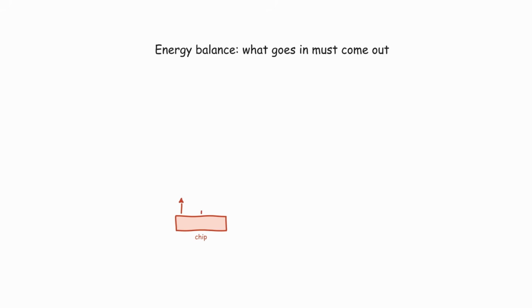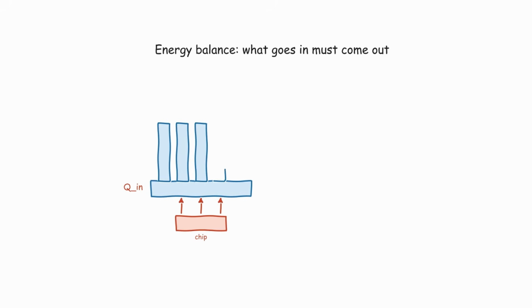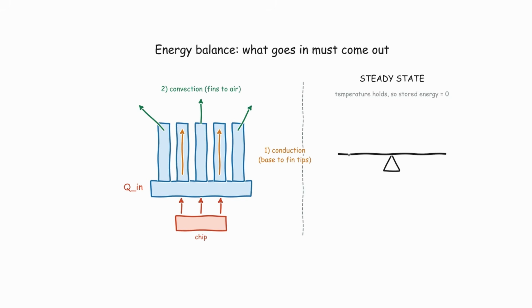So, does it make sense? Because before you ever trust a CFD result, you do a gut check. OpenFOAM integrates that wall heat flux for us and tells us the heatsink is dumping about 24.6 watts. And that number isn't magic, it drops straight out of the physics.